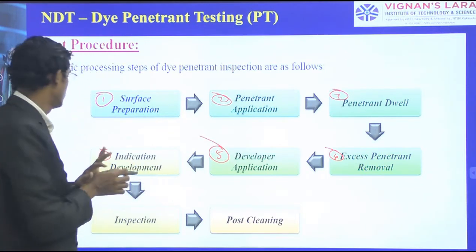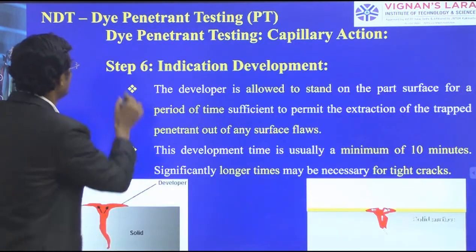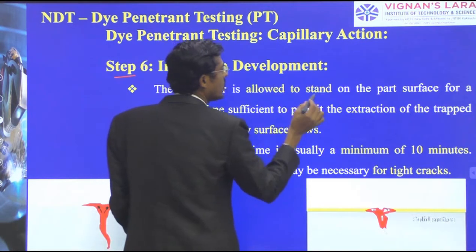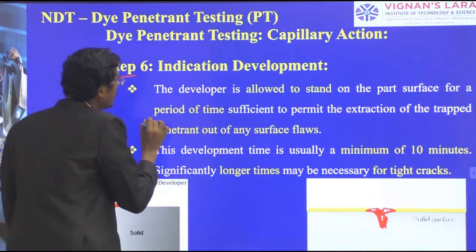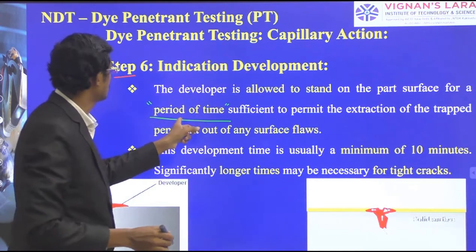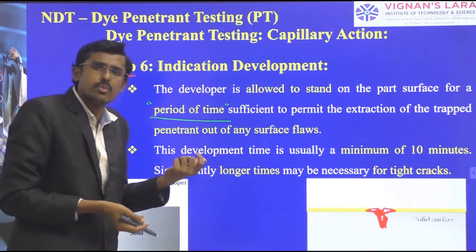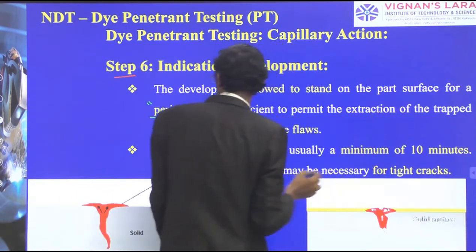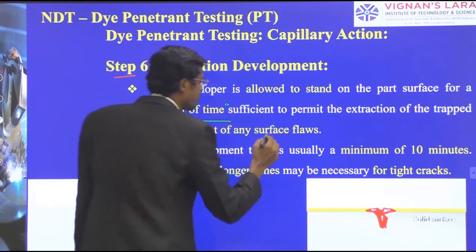Indication development: we are doing indication development. The developer is allowed to stand on the part surface for a period of time. So here also we are giving dwell time, some few minutes, sufficient to permit the extraction of the trapped penetrant out of any surface flaw.